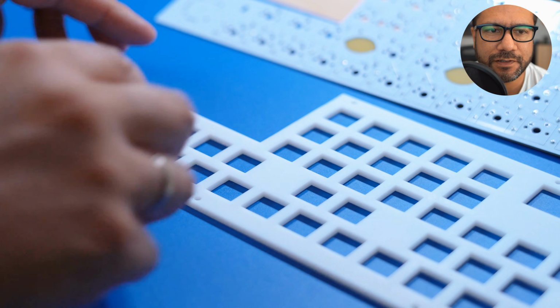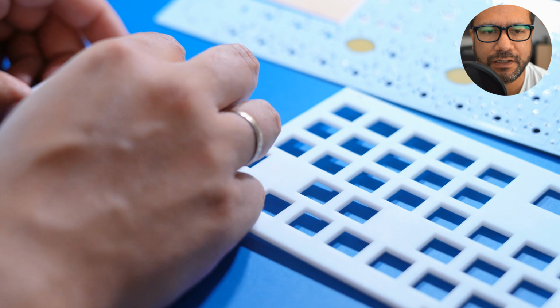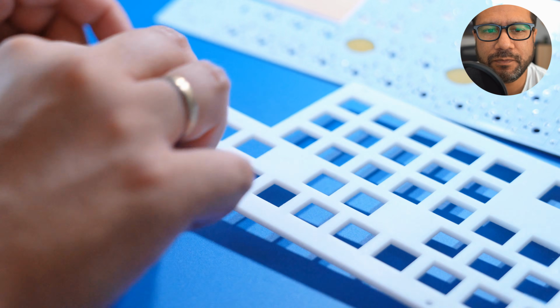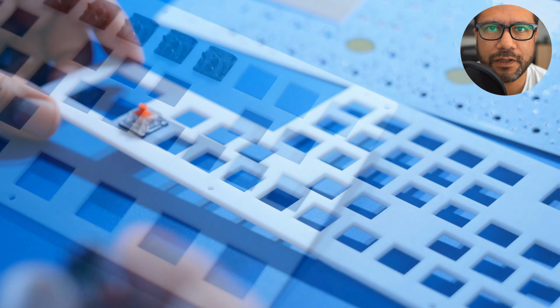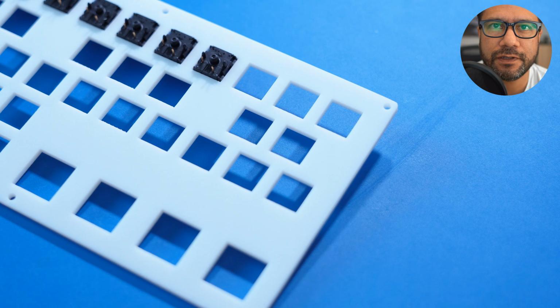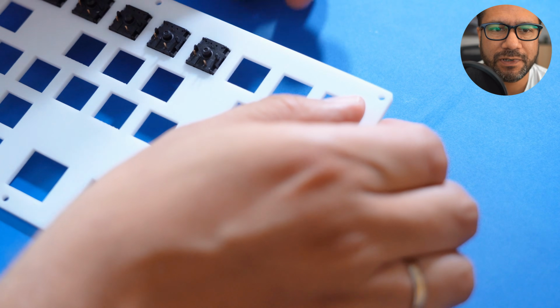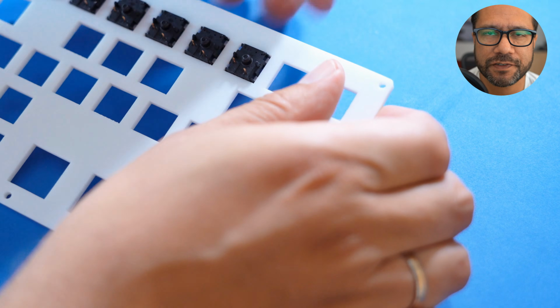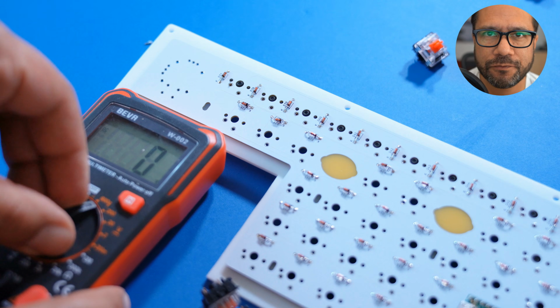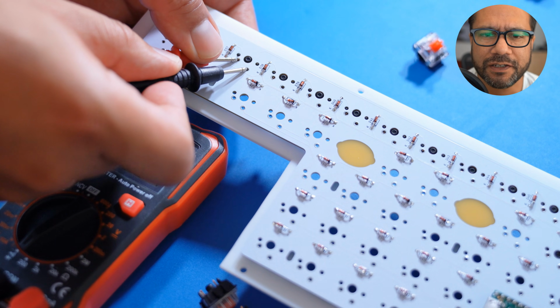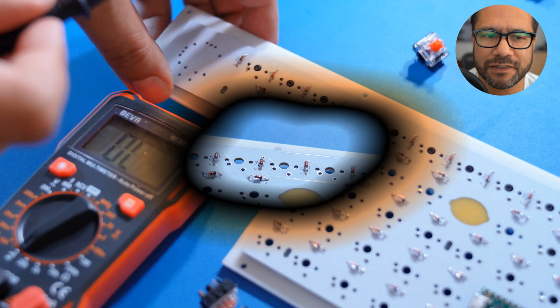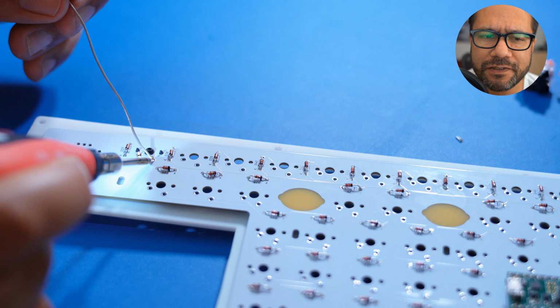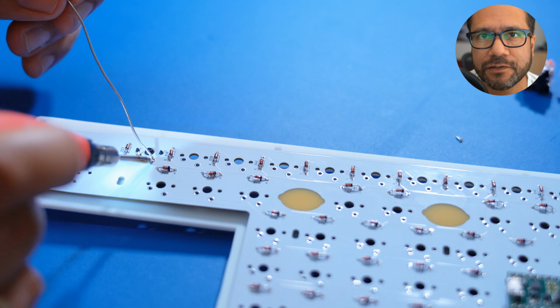Now it's time to solder the microswitches for the keys. Best is to begin by placing some of the switches on the upper part of the case as shown in the video. The pins are facing downwards or south. Now the project's webpage suggests to check every switch with a multimeter, but if you bought your switches new, that's not necessary. Now align the switches on the PCB and start soldering.